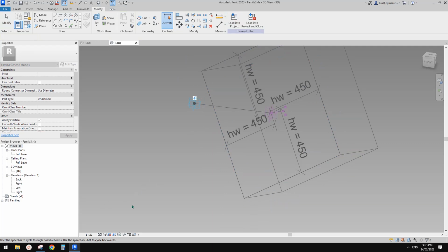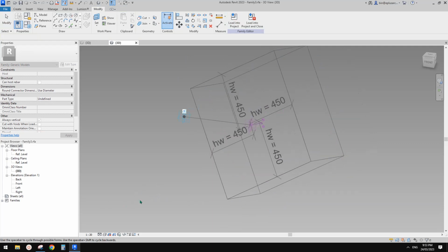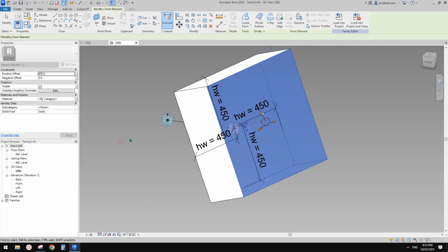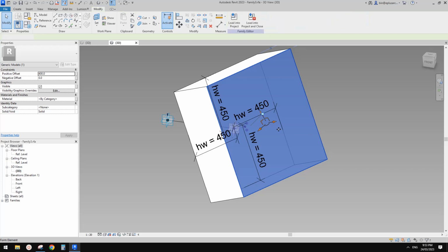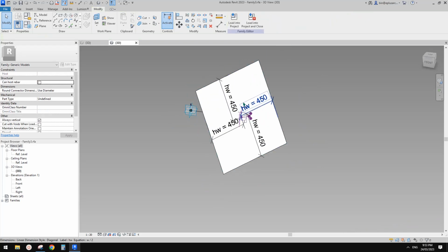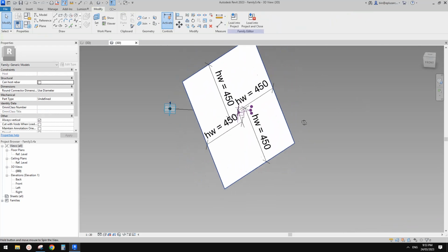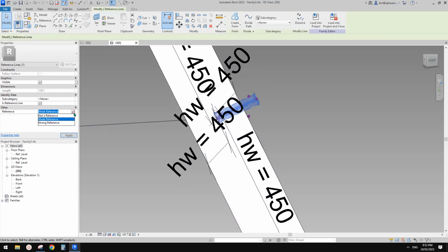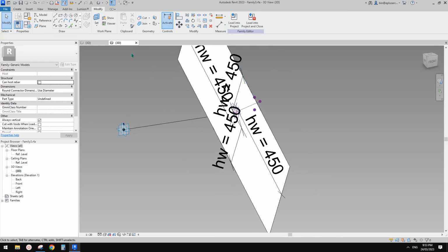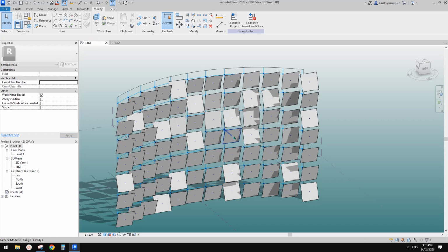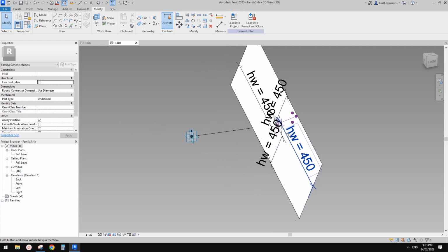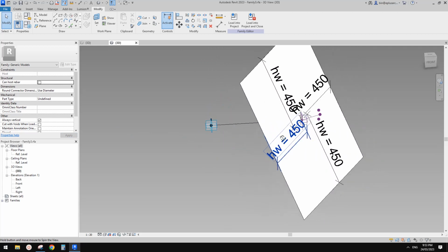Okay, so we now select this, create a form. Usually you will see an option. There will be two options. One is solid on the left, but I can't find it. Anyway, just click anywhere just to create a solid, and I'll just delete the surface. So we have this surface, and also I'll just make this not a reference, so later when we place into here, there won't be a lot of invisible lines that you can accidentally pick. And I think this is it.